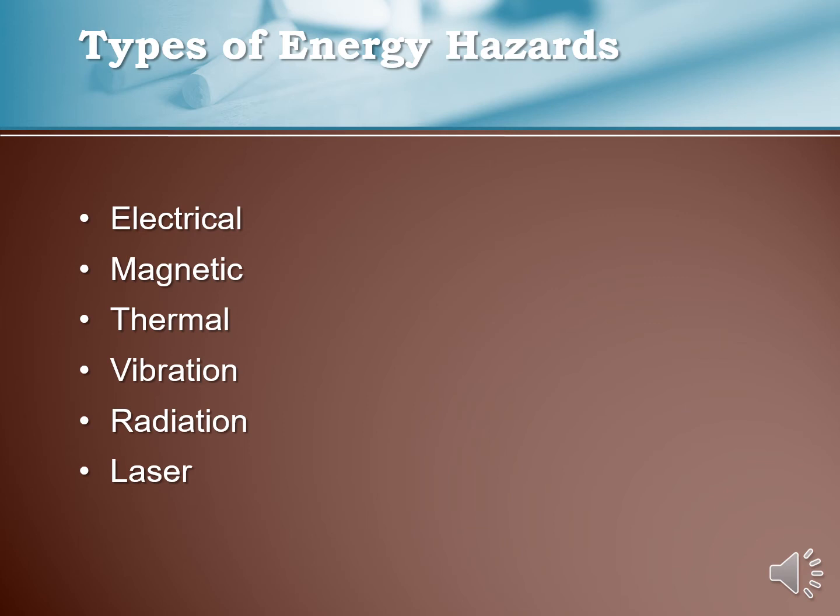Some examples in our workplace may include electrical hazards, such as extension cords that are used as permanent electrical wiring, broken third prongs on equipment, nicks in cords which leave the wires exposed, or receptacles that are placed near water. There may also be potential for contact with live electrical, and you may want to pay attention to whether proper lockout, tagout procedures are being employed where necessary.